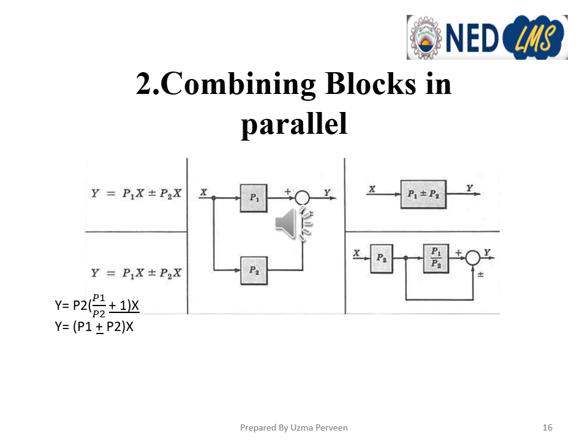Here in the second transformation, we can see that our forward path is actually replaced by a single line. It means that its transfer function is 1. So when we simplify this, it will become P1 upon P2 plus 1 multiplied by x, and x is already multiplied by P2. So this will become y equals P2 multiplied by P1 upon P2 plus 1 into x, and then when we open this bracket and simplify, we'll get y equals P1 plus or minus P2 into x.